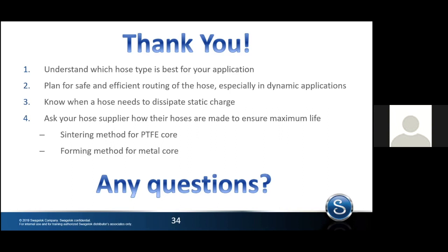And I think there's a last question about Swagelok metal hoses, and are they all hydroformed, or do we also, much like in the sintering, give you a set of options? We have options because we know that it's not always worth the additional cost. All of our hoses are hydroformed except our FM. So when you look at our catalog, our FM is mechanically formed. Great. So it's a better hose for a static application. So they can come to us for pretty much any need they have in that regard, I guess. That's right. That's the idea.